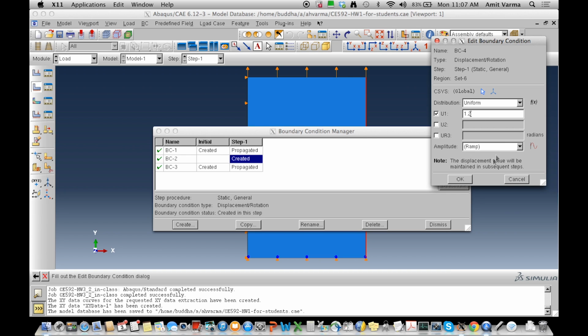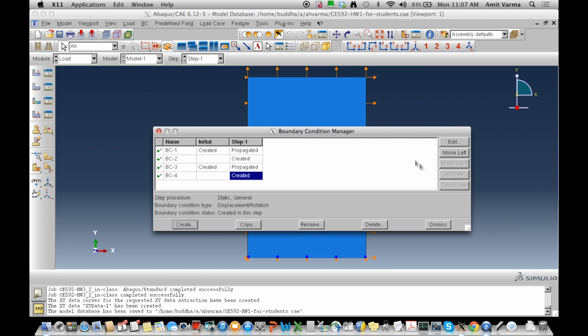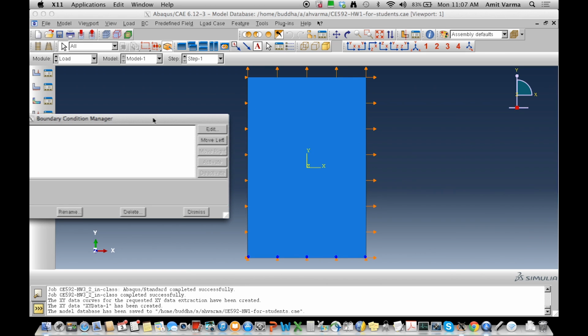I'm creating some of the simplest models for the world of plasticity. Right now I've got a biaxial loading case applied, and they're both being applied in the same step. I'm applying proportional loading, so to speak. The strain will reach 1% over that one step in 10 increments, and it will be a proportional loading. Why am I saying it's going to be a proportional loading? They're applied in the same step.